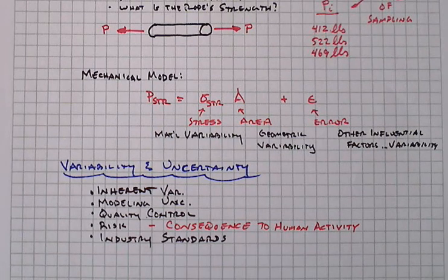And concrete, for instance, is a much more difficult material to control in terms of the variability we end up with in, say, the 28-day compressive strength of the concrete as compared to steel, where we can much more tightly control the variability that we end up with.